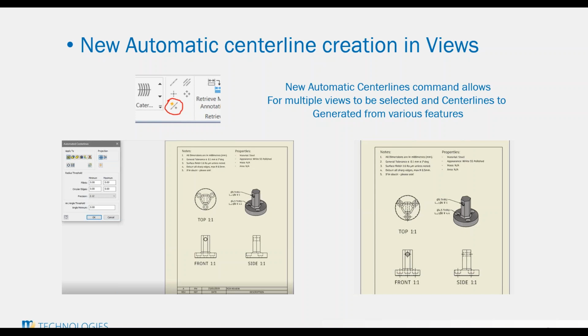I wouldn't expect anybody to do this, but if you actually set a sketch, say perpendicular to the diameter in there, and instead of punching a circle down through it, you decided to go in there with a rectangle and revolve it so it made a hole. This tool will actually pick that up because it is a revolved feature.